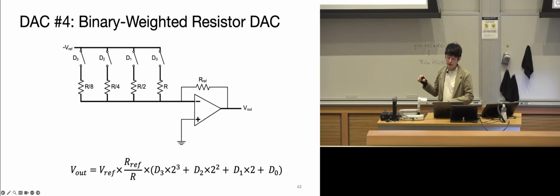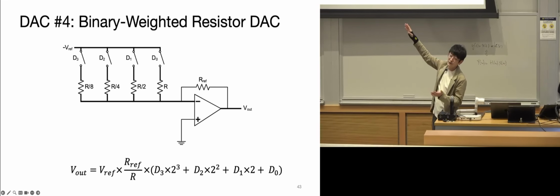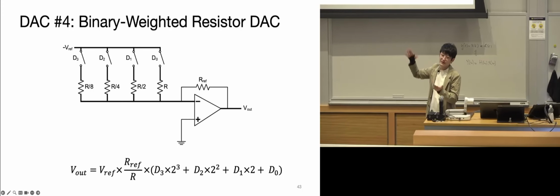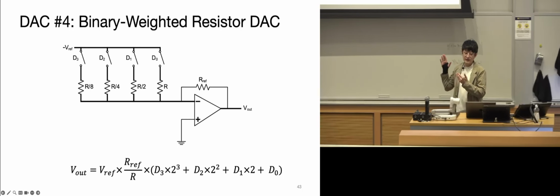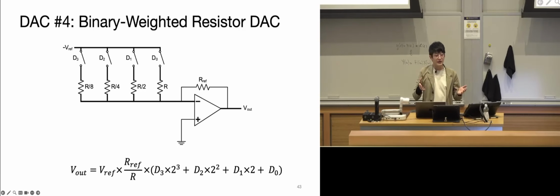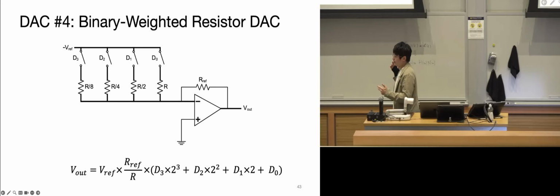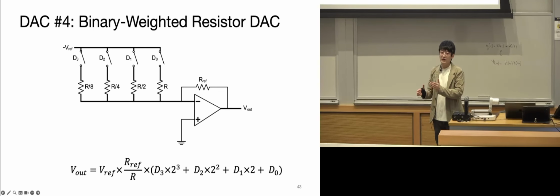It's essentially the same if you do R, 2R, 4R, 8R. It's just however you define your Rs, but usually it's in these binary ratios. Again, like we said, that's mainly for manufacturing consideration. It's going to make it easier, but still much harder than just using the same exact Rs.